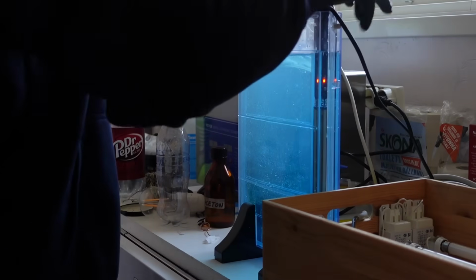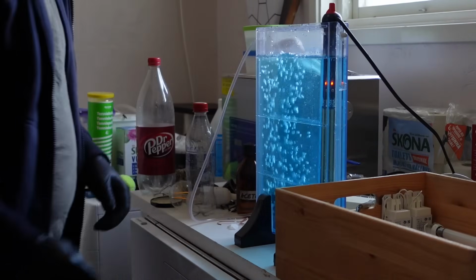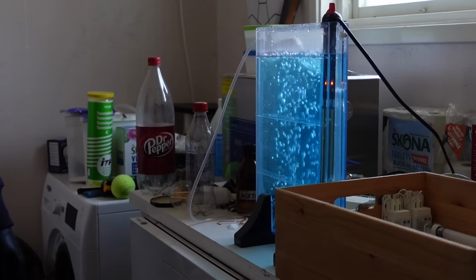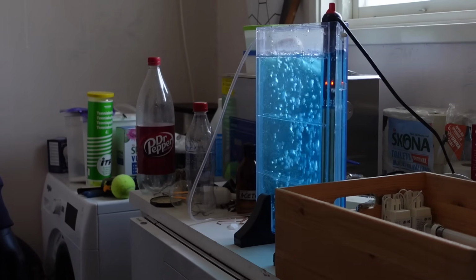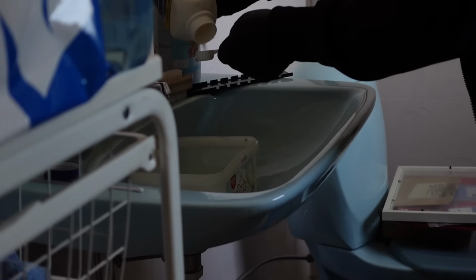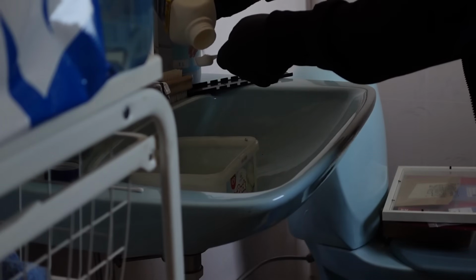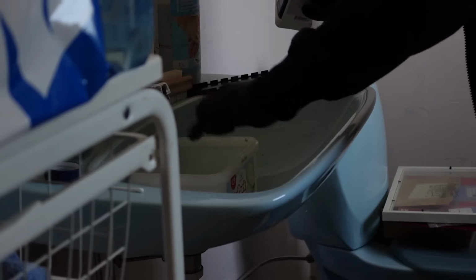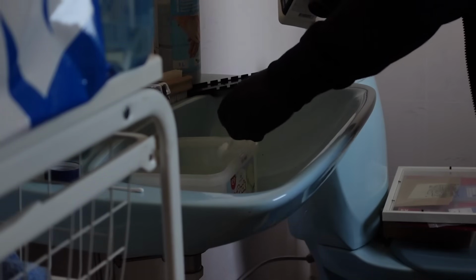With that added to the etching tank, we can turn on the heater. And don't forget the bubbles. If you don't have a heated tank, you could just carefully microwave the solution, I guess. With the tank up to temperature, we can prepare the developer. This is done by dissolving a teaspoon of caustic soda in a liter of water. The gloves and goggles are not for show, for this step it's absolutely required.